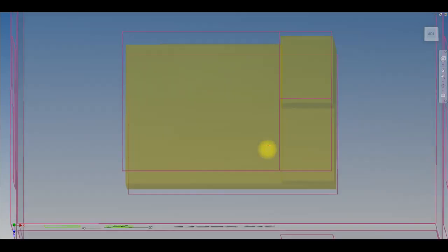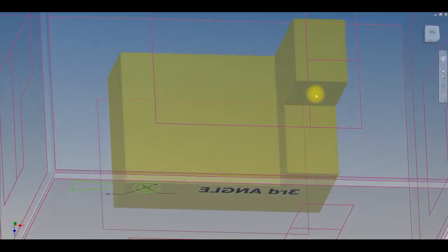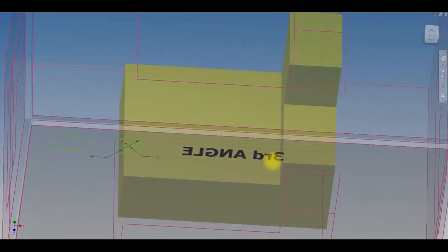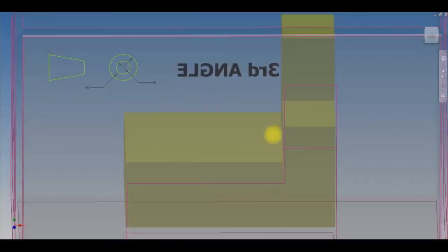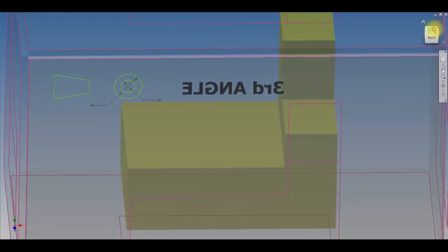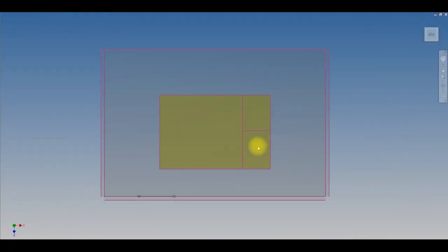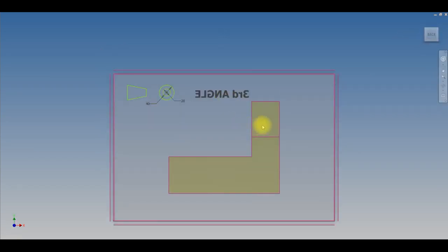But when we look directly down on top, we can only see those individual lines. We can see this edge here is this line. This line here is this whole edge. But you can't see there's a difference in height there. That's the reason why in two-dimensional drawings we have to give every view that shows the actual shape. If we only had a top view, you'd think that was only a rectangle. That's basically all you'd see is those two lines, but you wouldn't know how high those lines were until we put it in that view. You can see the height and the length.